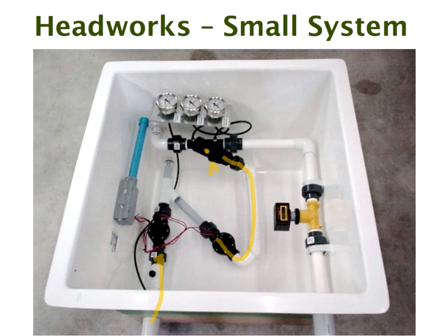from the pump tank, again through a solenoid valve here, and then through the filter, and you've got pressure gauges across the filter, so you're monitoring the pressure difference. There's a pressure gauge which is monitoring the pressure coming in and the pressure across the filter. Here you can see there and there. So that's the pressure entering the filter, and that's the pressure leaving the filter. Okay? And this is the pressure gauge which is going through there.